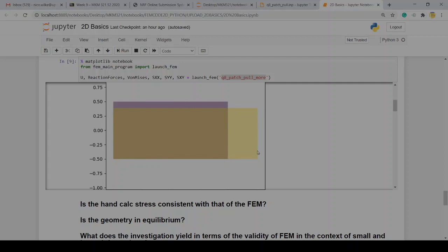If you want to use this updated area for your stress calculation, that's nonlinear finite elements. That means your stiffness matrix is a function of displacement, and you have to iterate to solve this thing. This is not what we're doing in this course. It's called nonlinear geometrical finite elements, and it exists, and it's a well-established theory, but we are not going to do that. We are doing linear elasticity in this course.